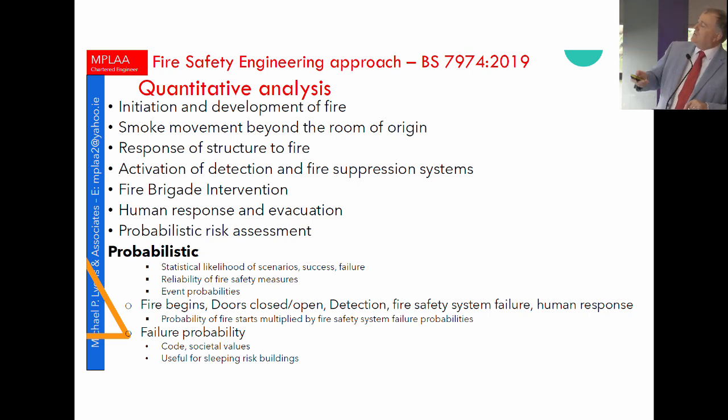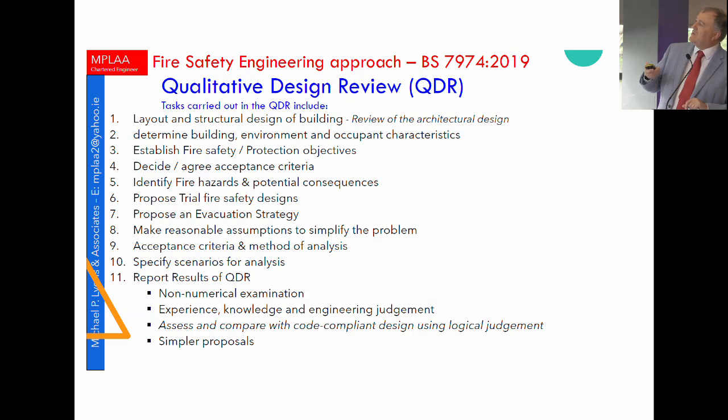So then we do our qualitative design. You determine the characteristics of the people in the building, the objectives of your protection, the fire hazards in the use of the building depending on its occupancy, the potential consequences when a fire occurs and the hazards that arise because the building is now burning compared to what it is in its day-to-day, the evacuation strategy that suits the actual occupants 24/7, 365 days of the year, Christmas Eve, New Year's Day, every single different scenario during the course